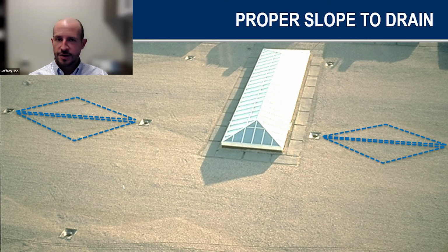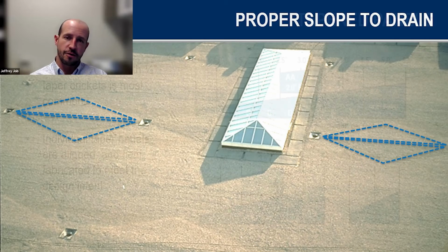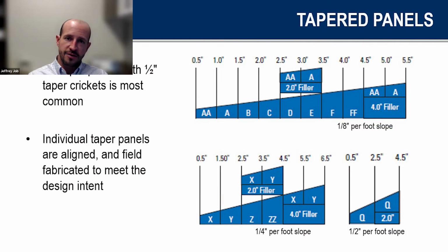So, for example, if we're going to attach our first layer, we're going to mechanically fasten it typically. Again, mechanically fastened tends to be the least costly option. So mechanically fasten that first layer, and then oftentimes we can come back and adhere the second layer. What that does is it helps break the thermal conduction of that fastener through the roof system. It's going to help offset your joints, so if there's any air movement through that roof system at the joints of the boards, those two components can have an impact on the thermal performance of that roof system, right?